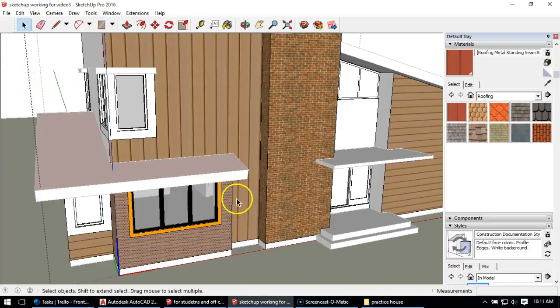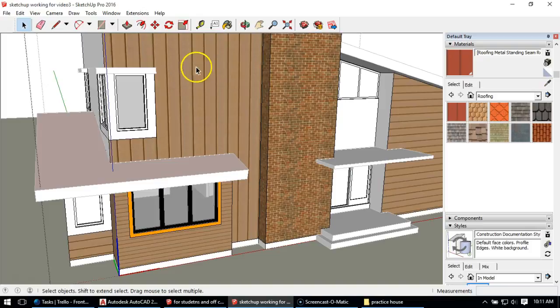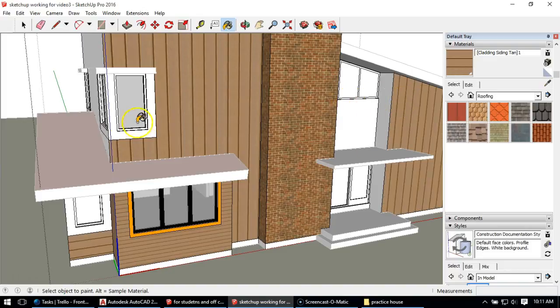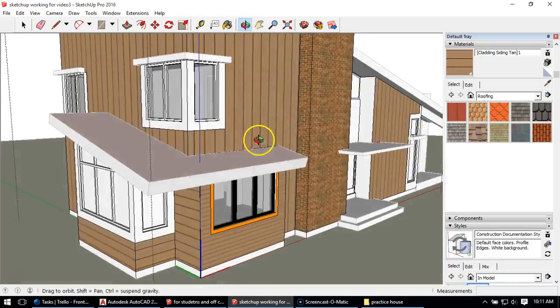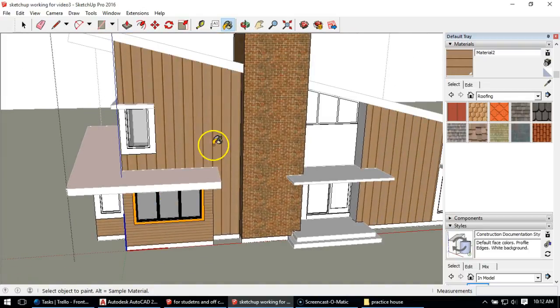Now let's say you've got these materials set up the way you want. How do you apply that to these other areas that I've already pasted that aren't finished, or maybe over here where I don't even have anything? Well, make sure you're in the group, of course. I'm going to go to Paint Bucket. What I'm going to do is hit ALT on my keyboard, and we'll notice that I've got the eyedropper. Now I'm going to click. Now I've absorbed all of those properties into the Paint Bucket, and so I can paint that, and it goes exactly how I want. And I can hit ALT again and absorb that property, and I can paint it there, and there, and it changes it.